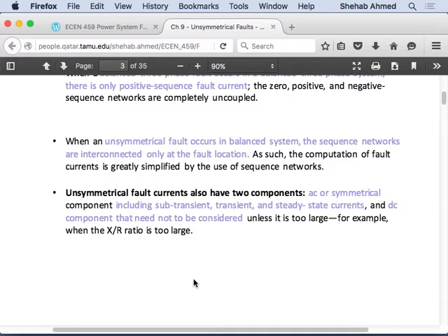And the structure of the circuit breaker is grounded, so you have to make sure that all your contacts versus ground are insulated properly. But voltage during the short circuit is not really a consideration, because when a short circuit happens, the voltage drops down. So voltage is an important consideration, but it's mainly during operation.